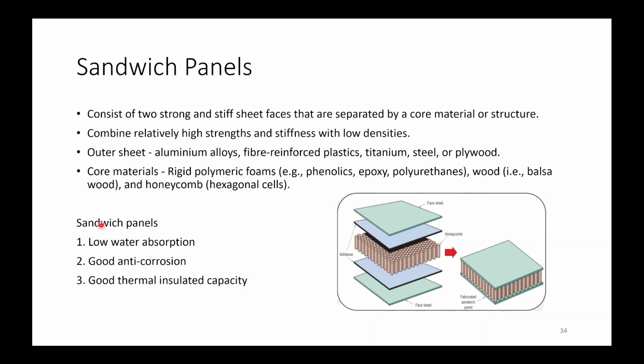Now these sandwich panels have a low water absorption problem, they have good anti-corrosion property, and they show good thermal insulation capacity. Because the foam that we are using will be filled with air bubbles, that always provides good insulation and also reduces its density.